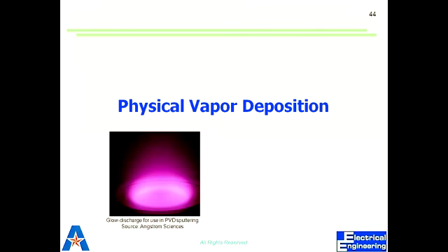And if you say I have deposited polysilicon, it should tell you what somebody would have used to do polysilicon deposition. It's CVD. If I say I already have metal and I deposit polysilicon, I deposit oxide, it should tell you whether I might have used LPCVD or PECVD. Does it make sense? Is it hierarchical or still abstract?